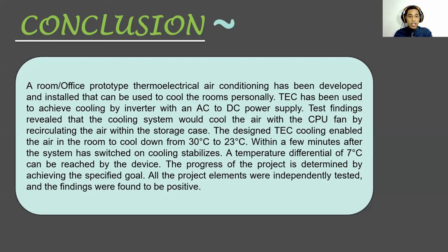Okay, next, in chapter 5, the conclusion and recommendation. For the conclusion, this prototype thermoelectric air conditioning has been developed and installed so it can be used to cool the room personally. The TEC has been used to achieve cooling with an inverter and an AC to DC power supply. Test findings revealed that the cooling system would cool the air with the CPU fan by recirculating the air within the storage cache or cooling area. The designed TEC cooling enabled the air in the room to cool down from 30 degrees Celsius to 23 degrees Celsius, as measured in the result.